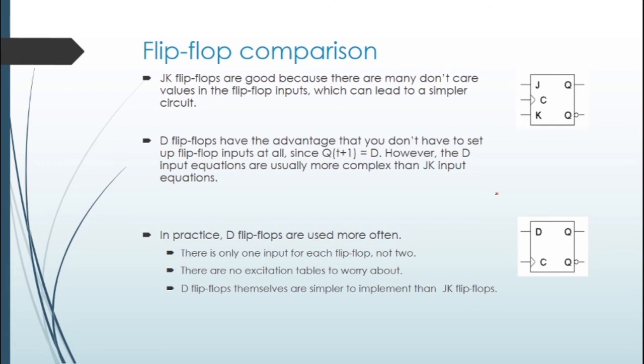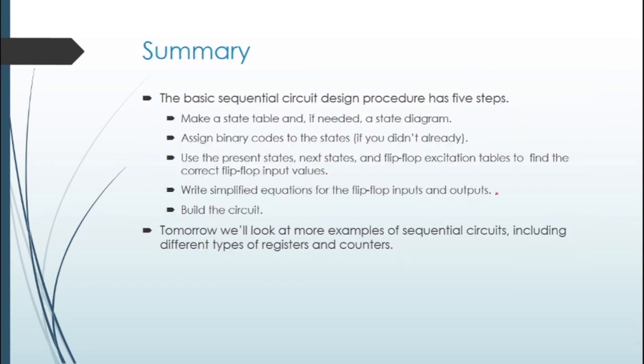So there are no excitation tables to worry about because we don't need anything. Whatever the next state is, the D input will be the same. That's why D flip-flops are preferred.